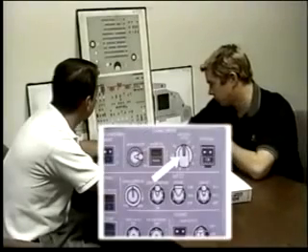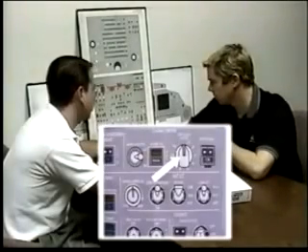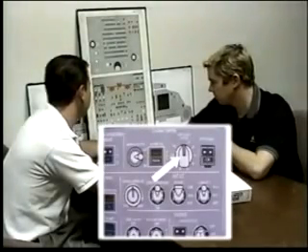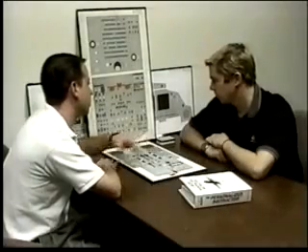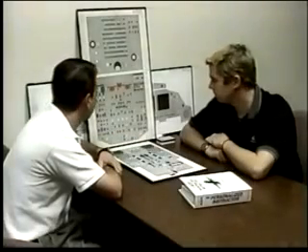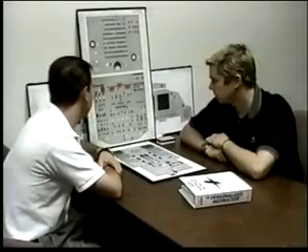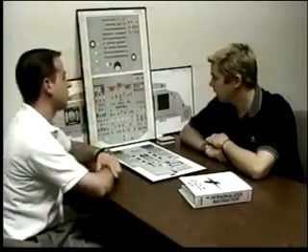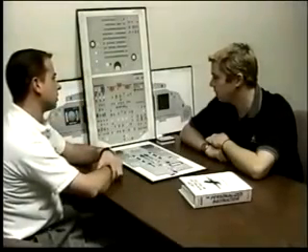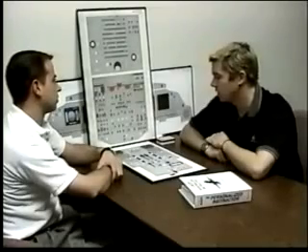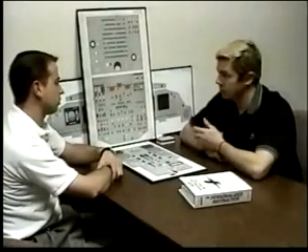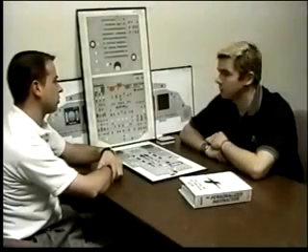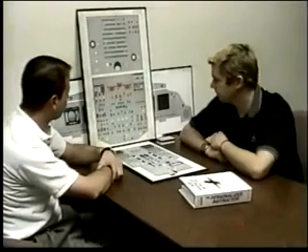For cabin pressurization, with the landing elevation selector in auto, where's it getting the landing elevation from for auto pressurization? From the FMGCs. Is there a time that you might take that selector out of auto? Yeah, anytime that I can't get the information from the FMGCs, which is either with a dual FMGC failure, or if the destination is not in the FMGC database.